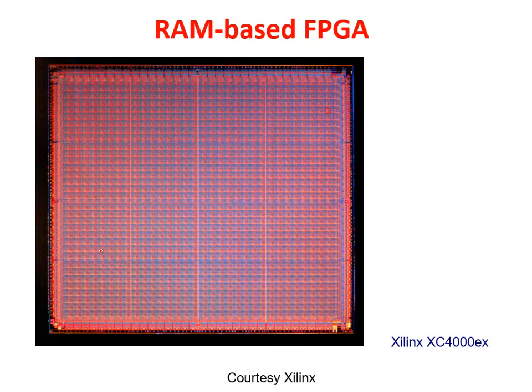And this, just to have a pictorial view, is the image of an FPGA with SRAM programming, by Xilinx in this case. You can see the structure is extremely regular. Each of those squares is a small processing element containing some pieces of logic and some pieces of memory, interconnected together.